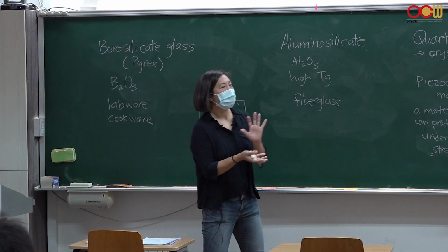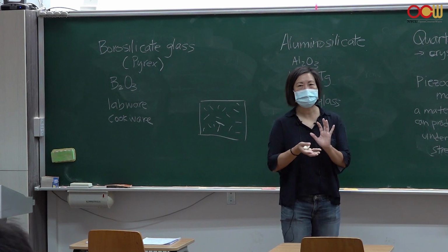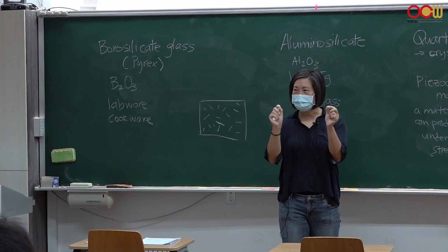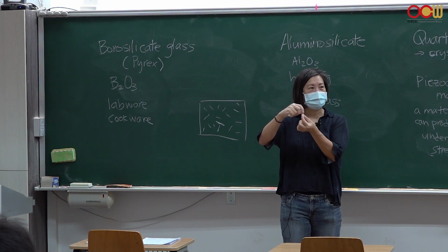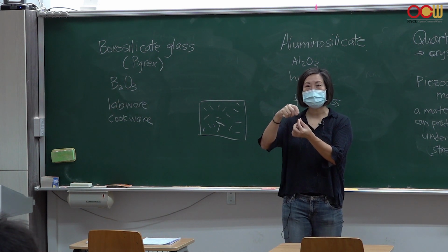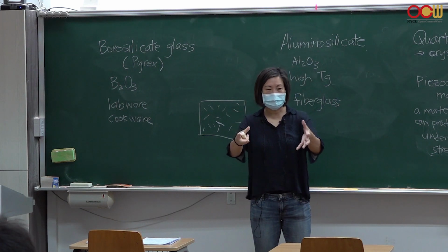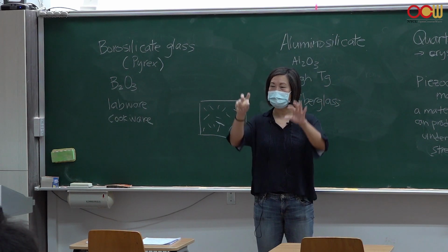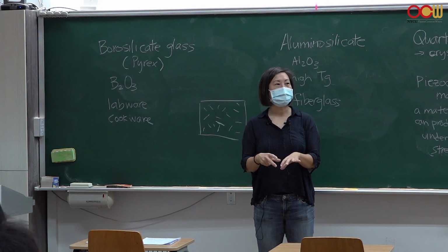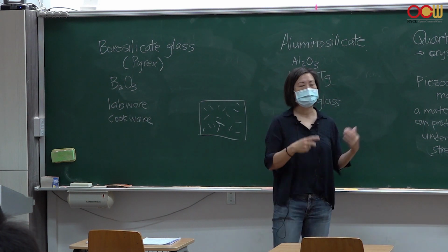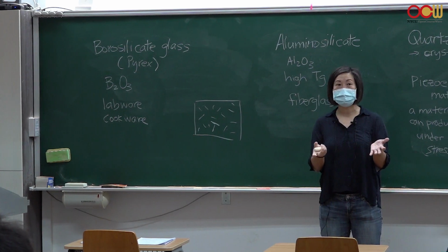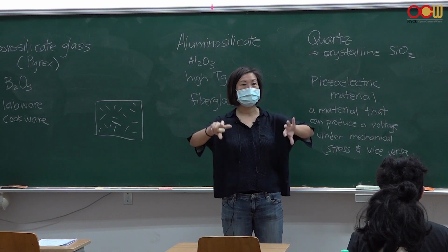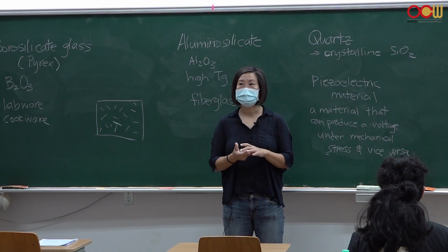It's not green, but it's called the green body, and you put it in the furnace, and the little pieces of particles will start to grow together through diffusion, so they'll connect. So when you take your ceramic out of the furnace, it's actually not individual particles packed together anymore. It's connected, by covalent or ionic bonding, depending on what you're using. And it will be very, very strong because of that bonding. But it does take time and high temperatures for diffusion and that growth to occur.